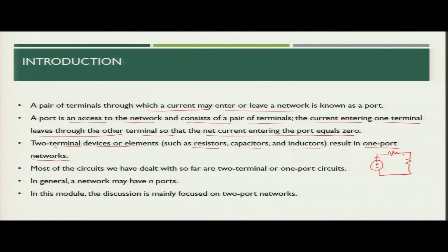So, now if you see, when you create the Thevenin equivalent, you generally represent it as Thevenin voltage and the Thevenin resistance, and then you see that the RTH is nothing but when you look into the network from the port, what value of resistance you will see.